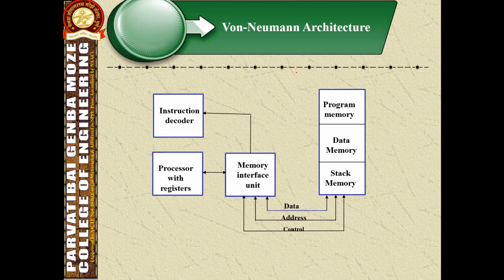And one disadvantage of Harvard architecture is that two sets of buses are needed, and therefore a relatively complex bus structure. Due to the different memory organization, the bus structure is complex and does not allow the size of the data and program to be adjusted flexibly and dynamically, as they are stored in different physical memory spaces. Some examples: the Intel MCS-51 family of microcontrollers has a Harvard architecture, because there are different memory spaces for program and data and separate buses for address and data.